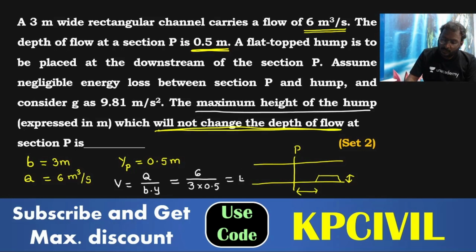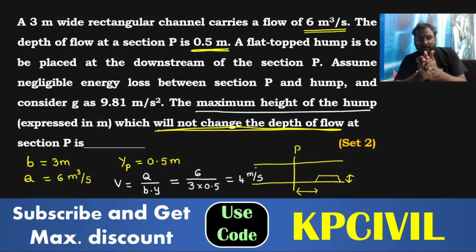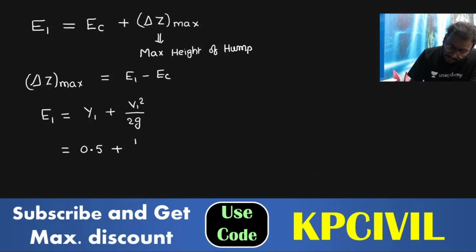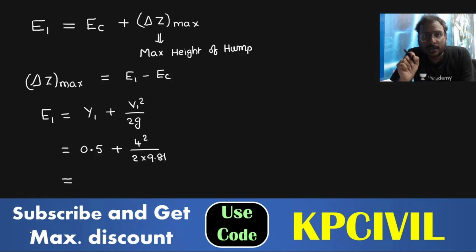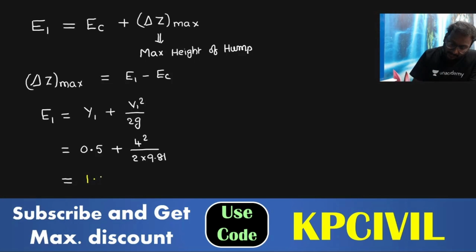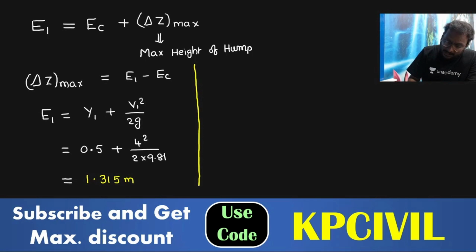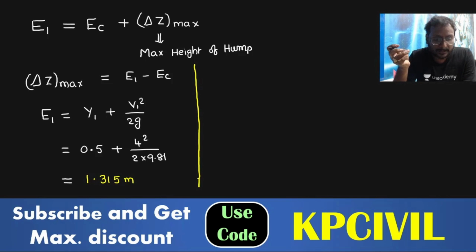Velocity is equal to 4 meter per second. Q by BY: Q is 6 meter cube per second, B is 3 meter, Y is 0.5, giving 4 meter per second. So 4 square by 2 into 9.81. E1 is 0.5 plus 4 square by 2 into 9.81. You are getting E1 as 1.315 meter. Energy at P, E1, is 1.315 meter.